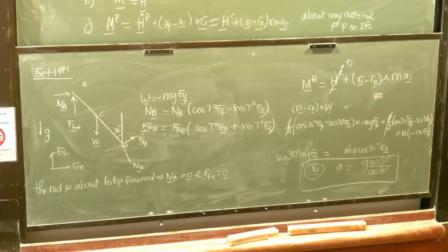I'm one equation away, but I need to plug in and calculate the cross product. Okay, great. You got one scalar equation. So if you project this along EZ, that's one scalar equation for the two unknowns, friction and normal force. You need more equations, which is going to be the balance of linear momentum, F equals MAC. That's 2 more equations, 1 more unknown, so you have 3 equations, 3 unknowns that you can solve for.